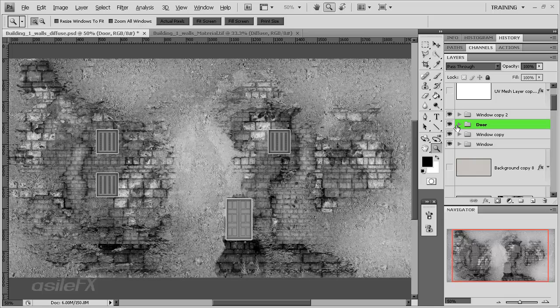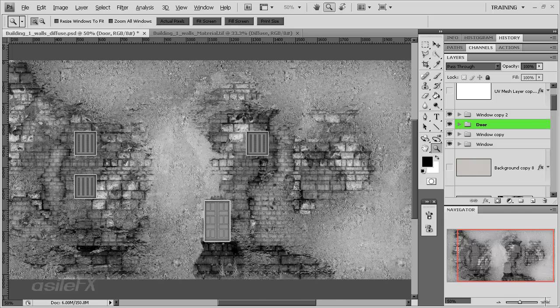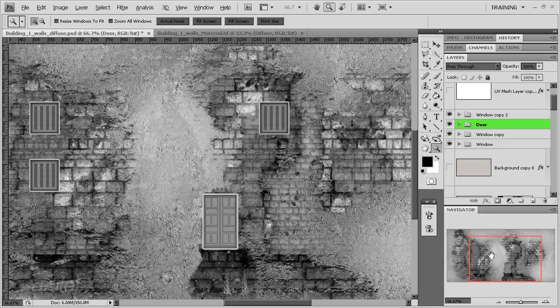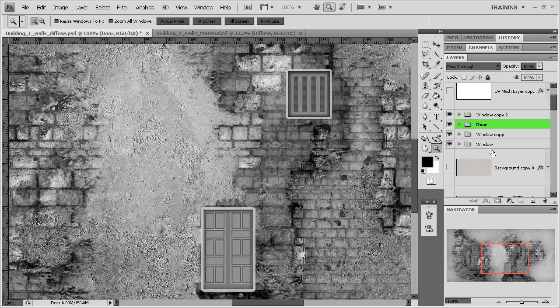So just creating this height variation. Basically what we're doing is just creating a height map to generate a normal from. And I'm going to be using the NVIDIA Normal Mapper tool, which is a filter that only runs in the 32-bit version of Photoshop and not 64-bit. Although it does work for versions, I believe any of the CS versions, at least CS2+, and that's free, available from the NVIDIA site. There's links included with the training.